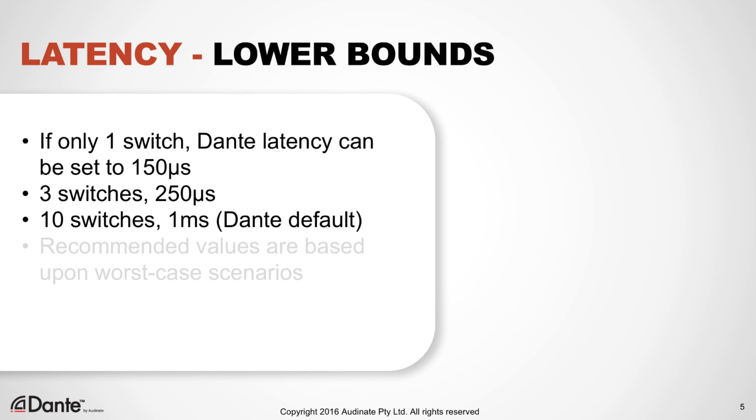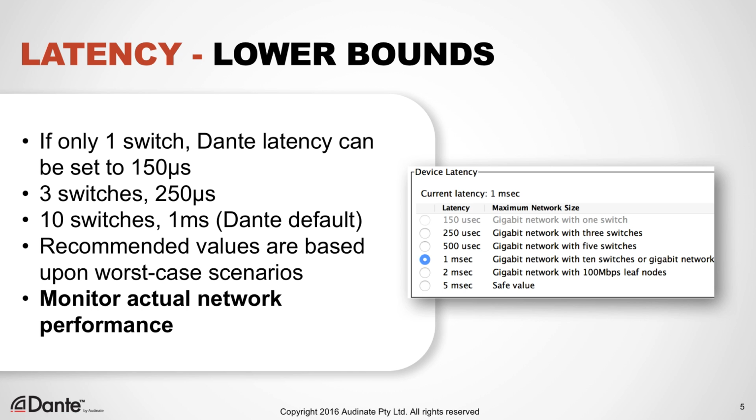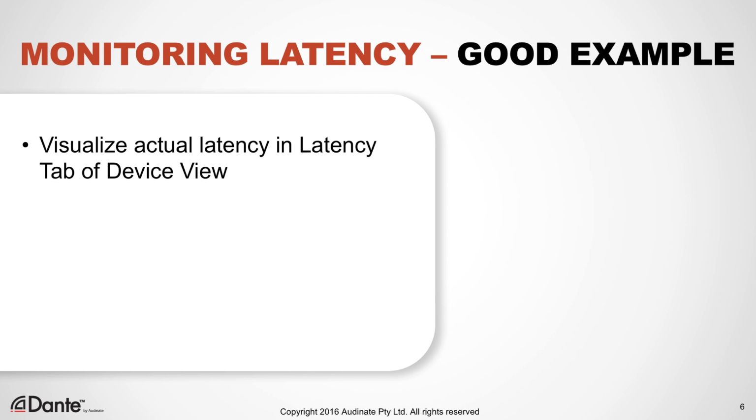It's important to note that the recommended latency values, while already very small, reflect worst-case scenarios. In many cases, you may safely use lower latency settings than the recommended values in Dante Controller. The latency monitor in Dante Controller shows you the real status of latency and is the best indicator that you have configured to work well on your real-life network.